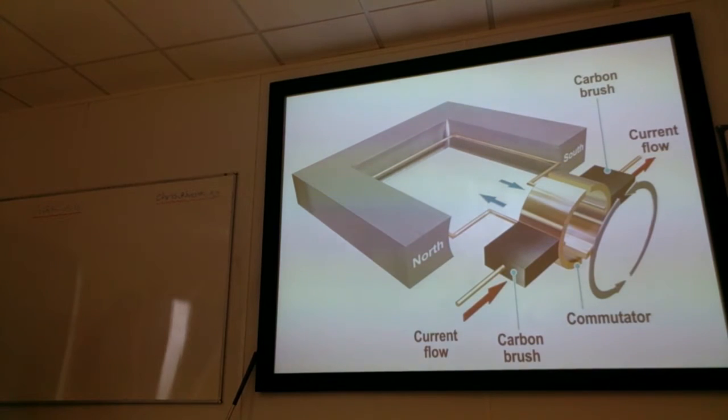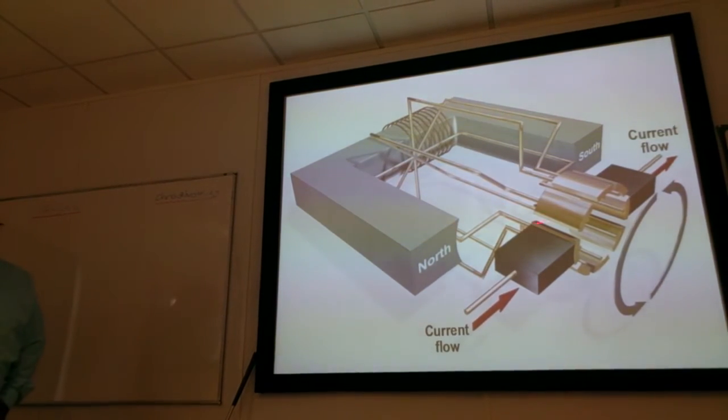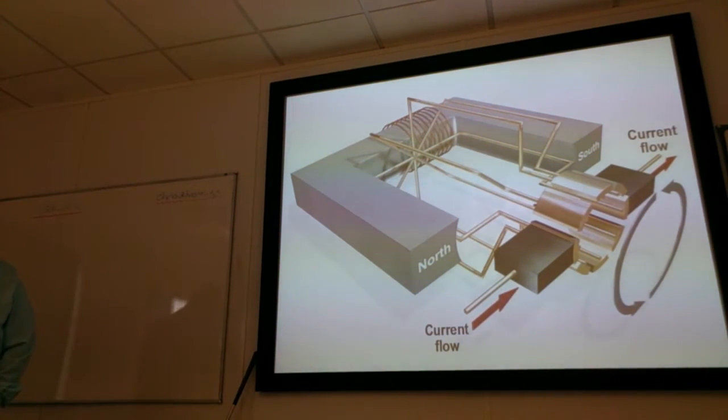Actually that's not enough. That would produce some fairly feeble movement, a bit like Faraday's first motor, you know, a bit of wire whizzing around in a pool of mercury. What we do is we put lots of coils, each one of those is a complete circuit from there right around to the other side, and we put it inside a very powerful electromagnet, so we control that by a winding on the magnet. That means we've got control of that, other than just leaving it to a permanent magnet to do the job.